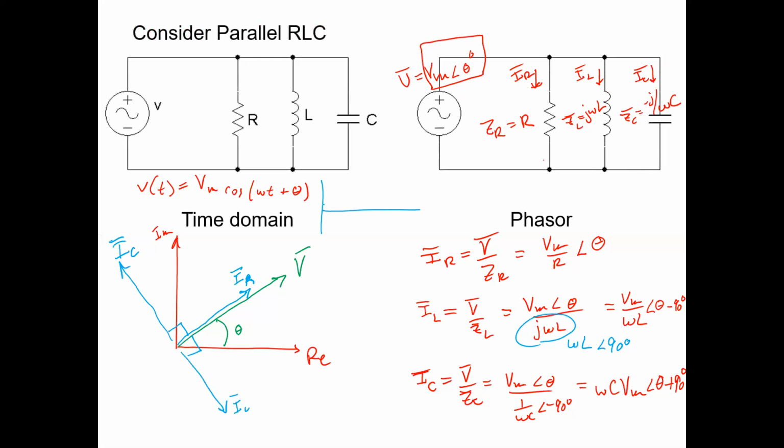But if your voltage was something like this, maybe if this is V, it's rising, right? The inductor is going to catch up to that 90 degrees later. So the inductor is going to be 90 degrees behind that. It's going to be something like the distance of a quarter of a period. So it's going to kick in here, and it'll do something like this.